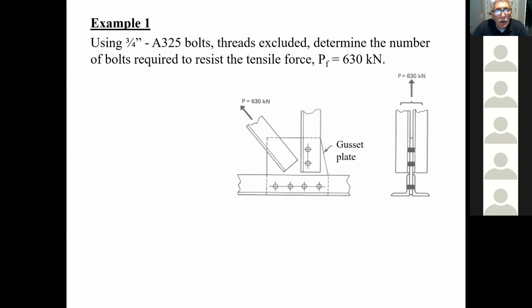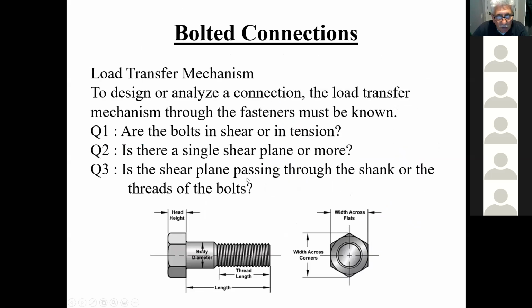Okay. So now, this is what we have, and it's nice that we all understand the little drawing. So now, if I go back to my first slide, does the first slide pop up for everybody? Does everybody see the load transfer mechanism? Okay, so to design or analyze a connection, the load transfer: are the bolts in shear or in tension? Can anybody answer that? The bolts that are going to be used to connect the angles to the plate, are they going to be acting in shear or in tension? Shear. That's right.